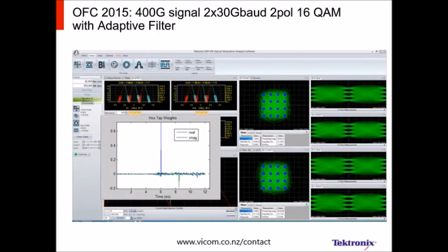And I wanted to point out a couple of things here. One is all the signal metrics. You can't really read them very well in this figure, but we're going to tell you how square the constellation is. That's called the quadrature phase error. We're going to tell you how well centered the constellation is, if it's shifted up or left, right, if it has any DC bias to it, which is called the IQ offset. We're going to tell you if it's longer than it is wide, which is IQ gain imbalance. But these are all things you can measure with an optical modulation analyzer.